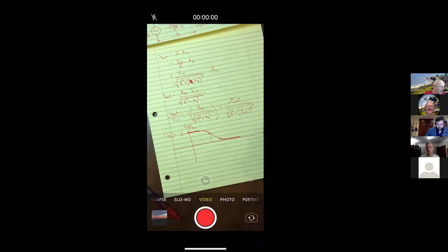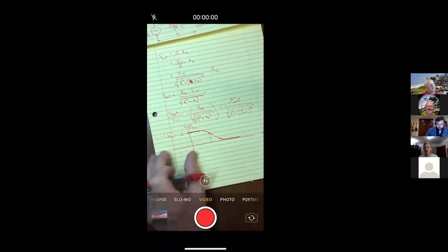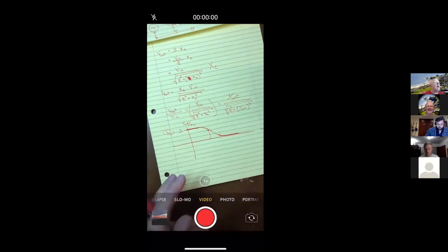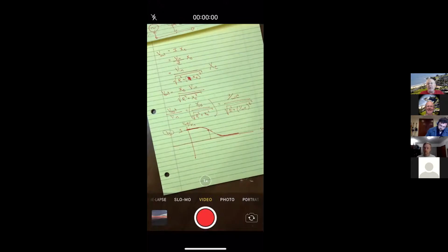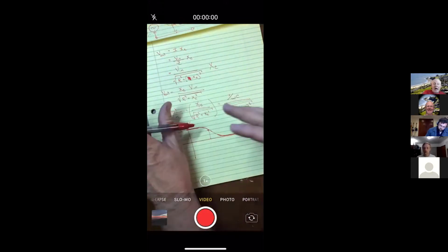So it kind of depends what you are after. That being said, you might see why we like to call this a low pass filter, because this is letting the low frequencies pass through. These are the ones that are going to be played at the speaker, the low frequency. And so hence the name low pass. We passed on the low frequencies, which is another way of saying we have filtered out or blocked the high frequency.